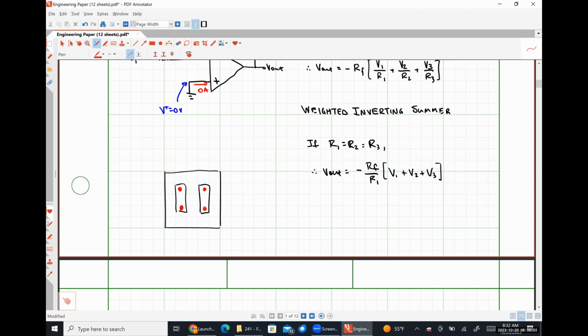If you apply a bias voltage across that nickel strain gauge, you're going to see that the voltage moves away from its equilibrium point when you deform this thing. An inverting summer would then be used to amplify all of those deflections and add them together to give you an overall idea of what the weight or the strain on the system is.